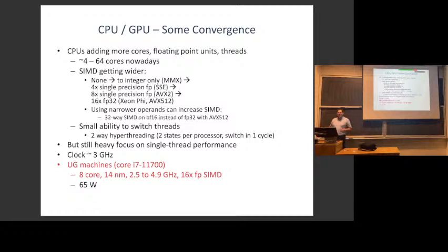Does that make sense? So wider and wider SIMD. Interestingly, it has some impacts. When you actually use these AVX 512 instructions, you're doing so much computation that it tends to increase the heat dissipation of the processor, and it has to actually drop its clock frequency. So there are some trade-offs here. You still get more done, but it's not perfectly linear because these chips are still power consumption constrained, so they actually have to drop their clock frequency if you do that many operations per cycle.